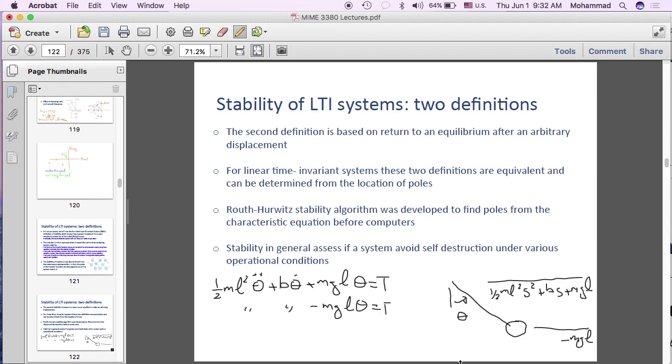So please continue this. What I'm asking you to do is show the poles of both models, recognizing that they're both representing the same system. One is the model of the system around theta equals 0. The other one is the model of the system around theta equals pi. And that's how we linearize it. We had to pick our neighborhood, if you remember. So this first model is about theta equals 0, and this is about theta equals pi.